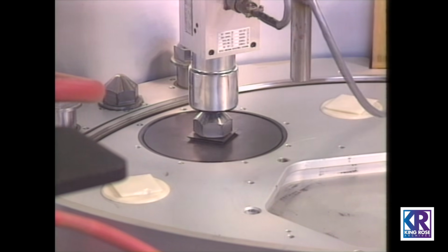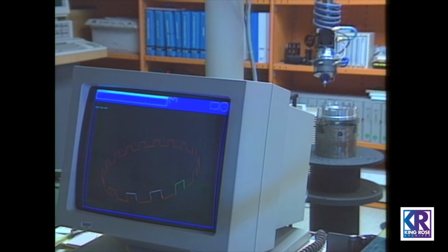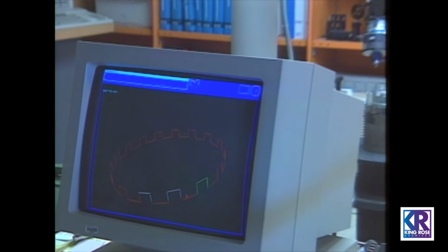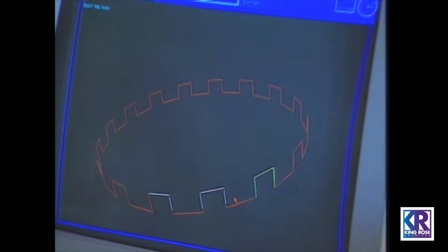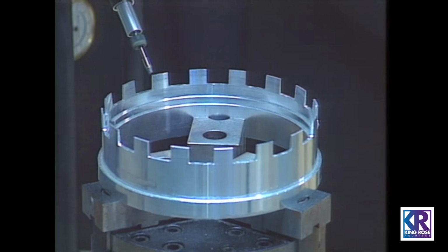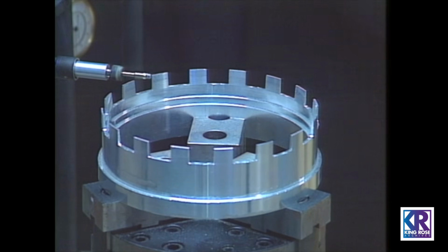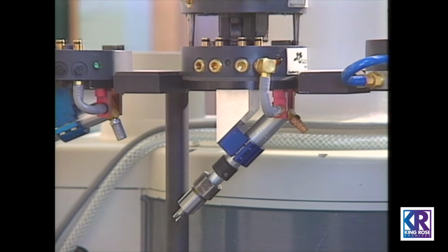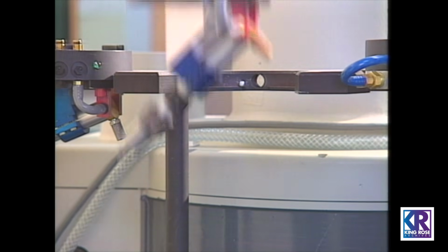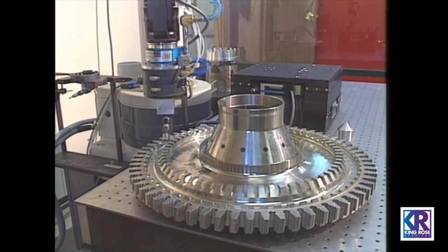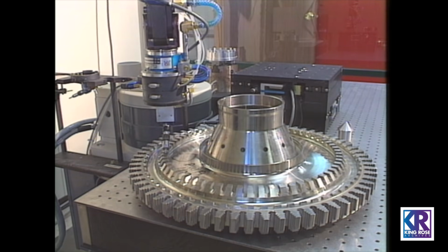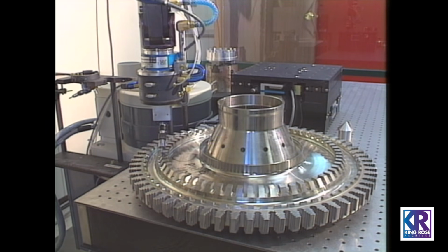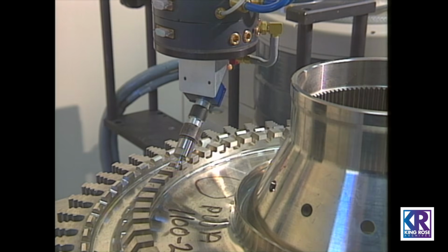In Sandia's robotic edge finishing laboratory, the automated deburring system reads the Anvil 5000 CAD database and writes robot control programs. The robot can deburr parts in 1/10 the time of manual methods while providing higher quality. Other Sandia research in controls and sensing will allow robots to be used for high-speed light machining, reducing fixturing requirements while providing new capabilities, such as automatic compensation for tool wear.